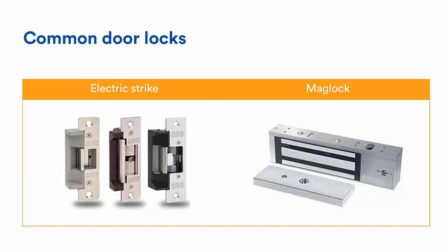Now, an electric strike replaces the regular strike for a lock set or panic device. It's used as part of an access control system to provide added security and convenience, such as traffic control and remote release. An electric strike is typically paired with a storeroom function lock set or panic hardware, so access is controlled by the electric strike.